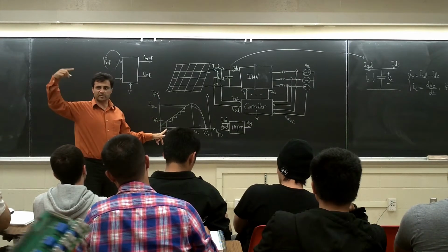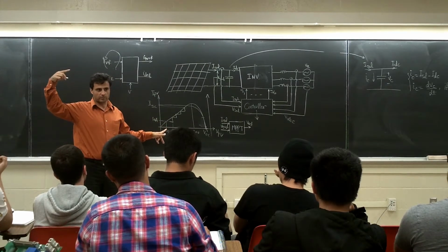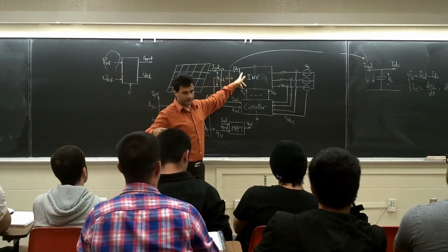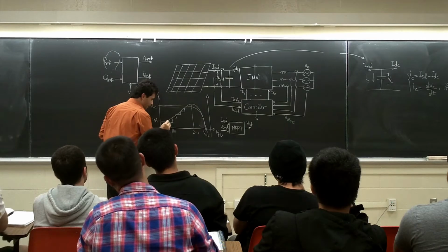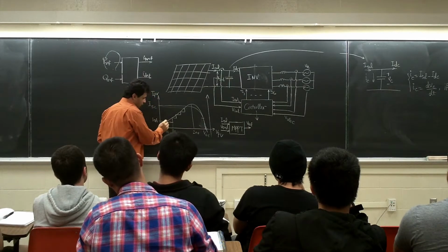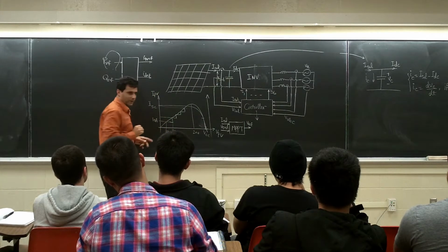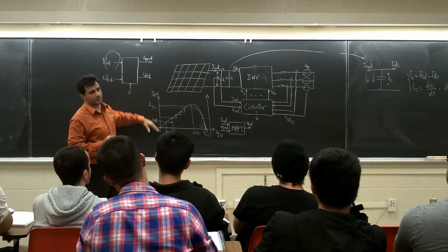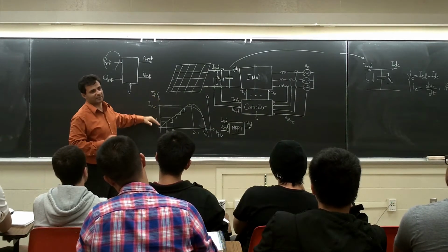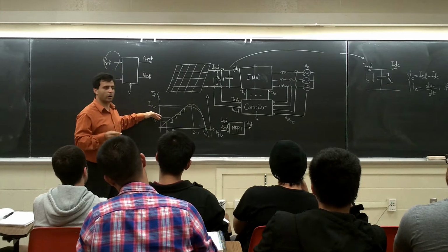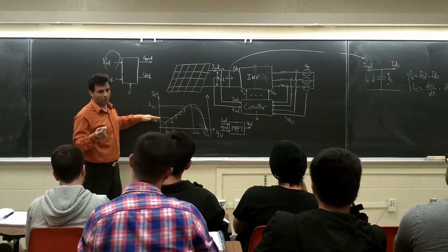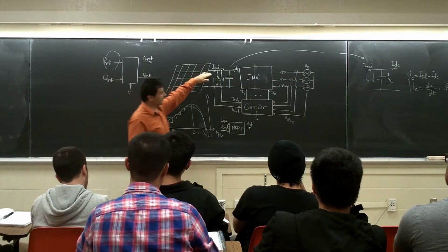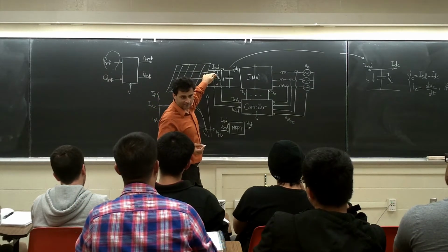I want to increase my DC bus voltage. What should I do? I should bring down this current, right? Basically, look here. When I'm going here, it's a little bit complicated, because the I short circuit is going to become more, but it's not going to jump. From here to here it is usually 8 amps. This step goes up maybe 0.1, 0.2 amps. This one is almost constant from this step to this step, so you say this current is fixed.